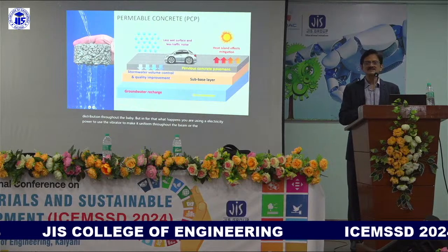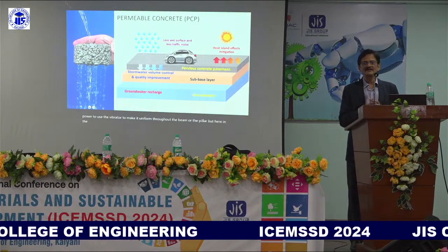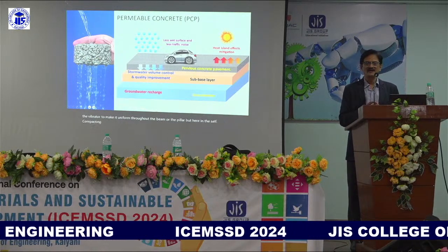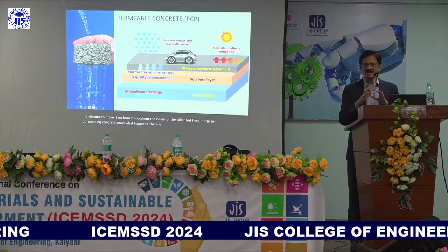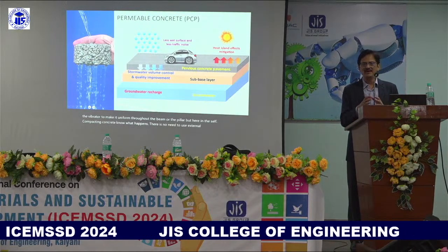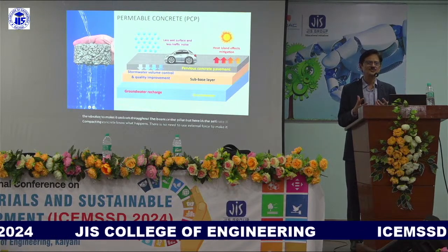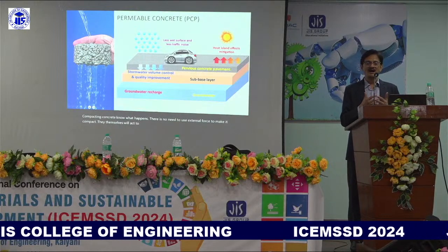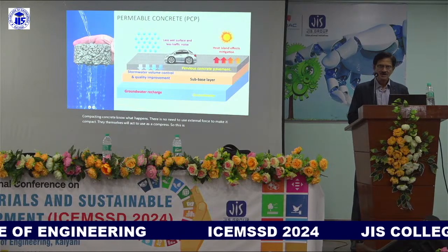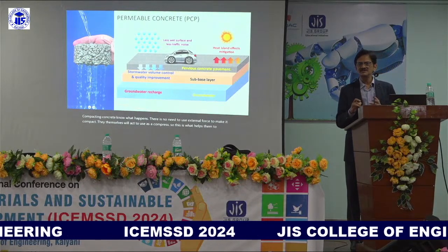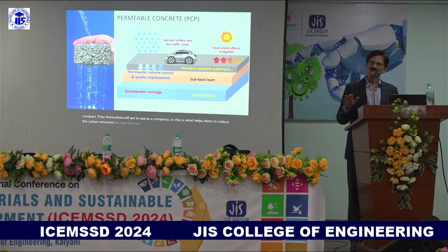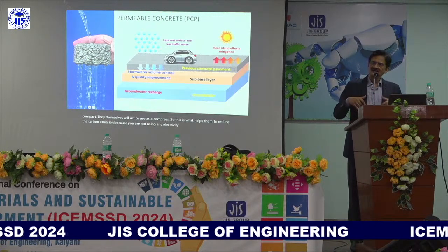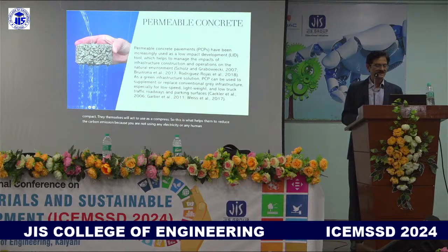But here in self-compacting concrete, you know what happens there? There is no need to use external force to make it compact. They themselves will act to compact. So this is what helps reduce the carbon emission, because you are not using any electricity or any human activity for such type of things.